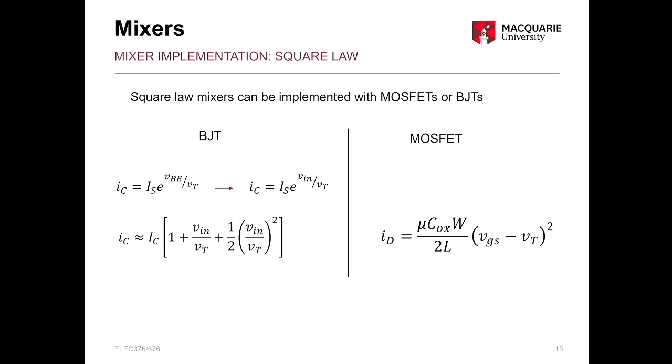So each power will contribute its own frequency component to the output, while in a MOSFET, it's only power 1 and power 2. There are no higher power terms there. So you've done in the lab that the MOSFET outputs are much cleaner when you look at the FFT of that. So MOSFETs are used for making mixers.